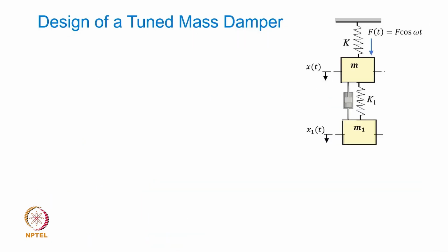people have devised a means of reducing such resonant vibrations at the two new resonance positions by suggesting to add a damper or a dashpot, okay, in the absorber system. So, the absorber is no more now a simple spring mass system, but a spring mass dashpot system. So you introduce an additional dashpot or a damping element to the absorber system, and the rest of the things